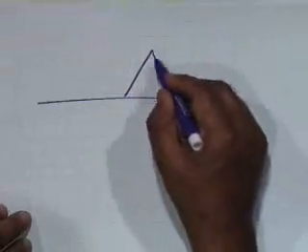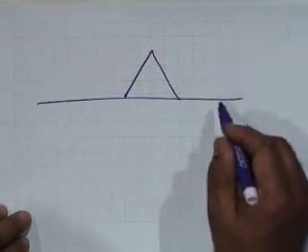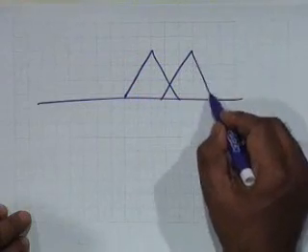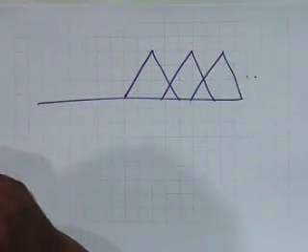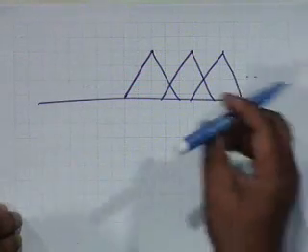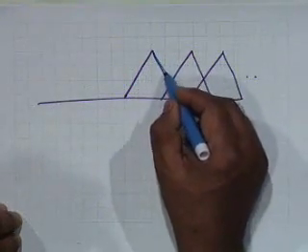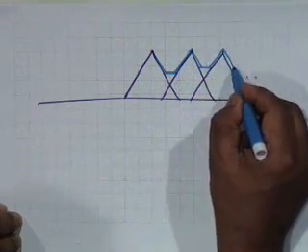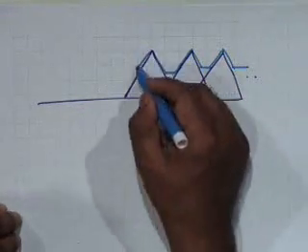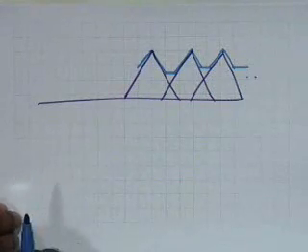The term had been introduced earlier. If we have a situation like this, this is the baseband spectrum, and then the next spectrum repeats like this, that is omega s has not been chosen correctly, then the overall spectrum becomes like this, and no amount of filtering, however carefully you do, shall be able to recover the original spectrum.